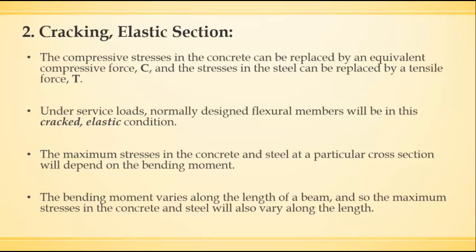Under service load, normally designed flexural members will be in this cracked and elastic condition. The maximum stress in the concrete and steel will depend on the bending moment produced by the applied load.